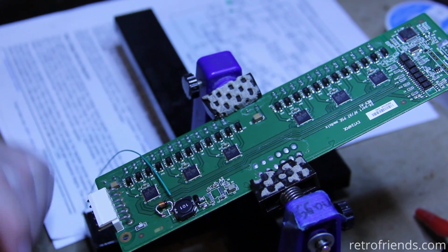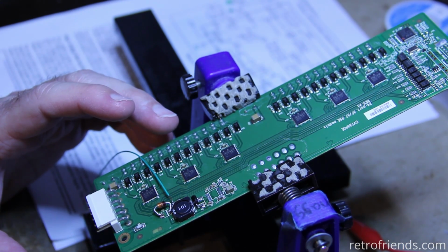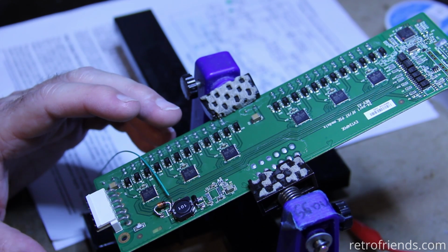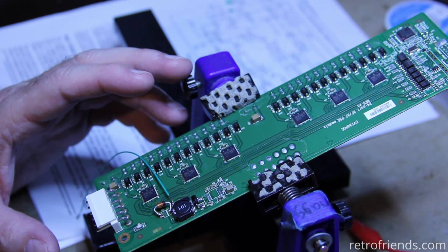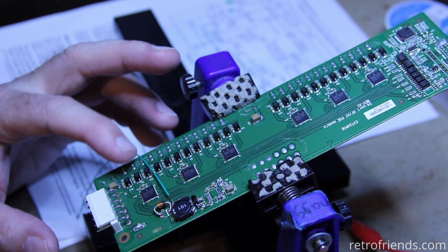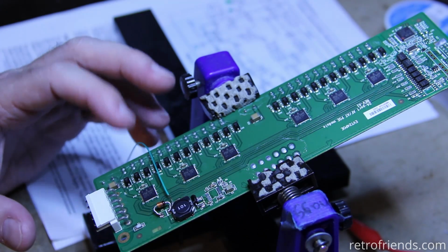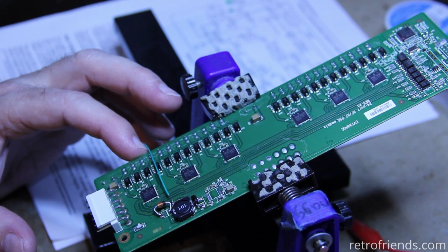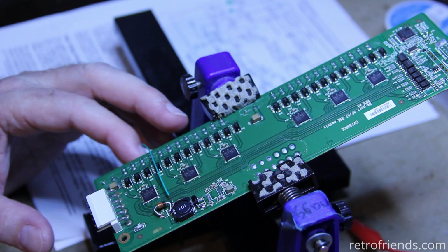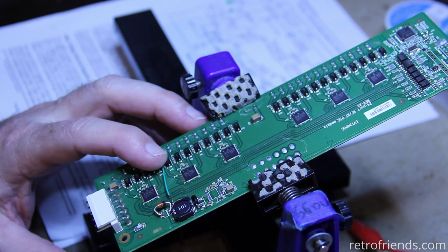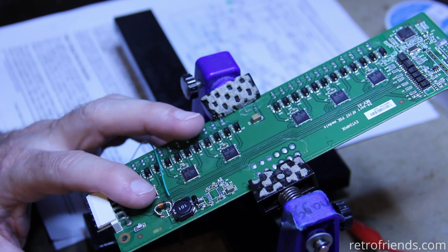When I test it using a diode tester in my multimeter, the multimeter puts like 1 volt through, and in one direction it'll pass electrons through, and in the other it won't pass anything, and you get a 0. But if my multimeter passed 5 volts through, I would have seen that it was passing electrons the wrong way. So that was pretty frustrating. I guess it's a good learning experience, but I spun my wheels. I spent a few hours on this before realizing that I had a bad Zener diode.